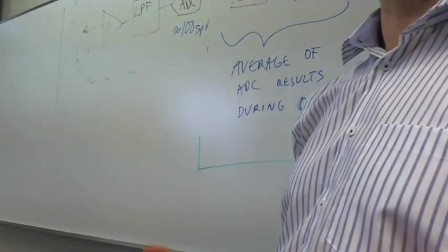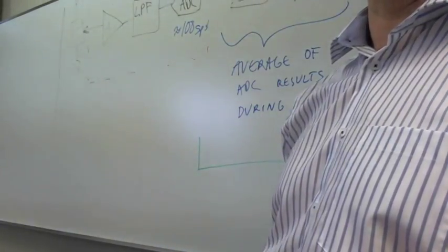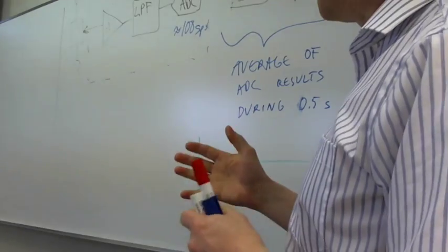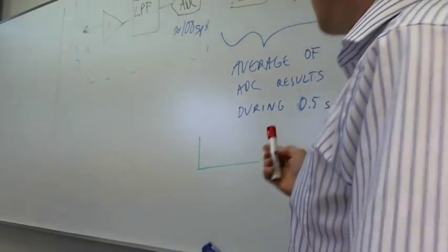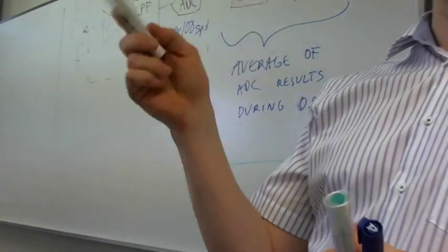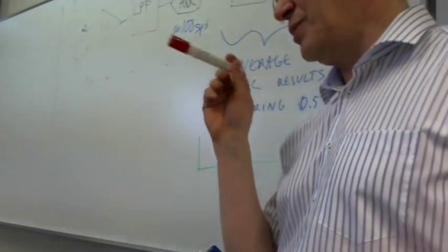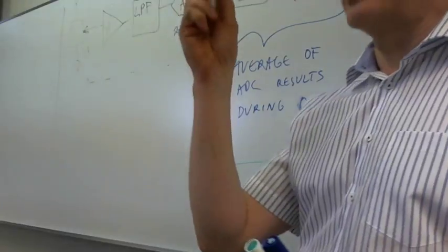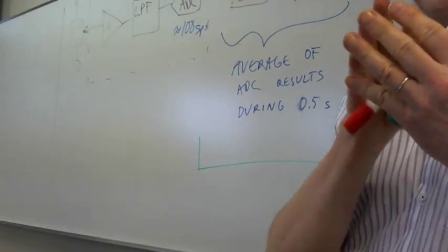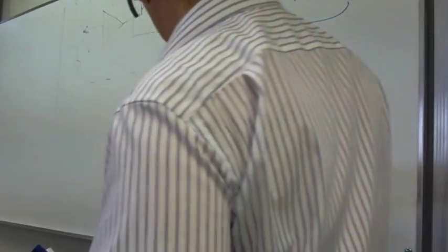I'm quite sure that in some cases the timing varies because you are doing something else in your main loop when the interrupt comes. So you do not necessarily get exactly 50 samples for this half second time frame.